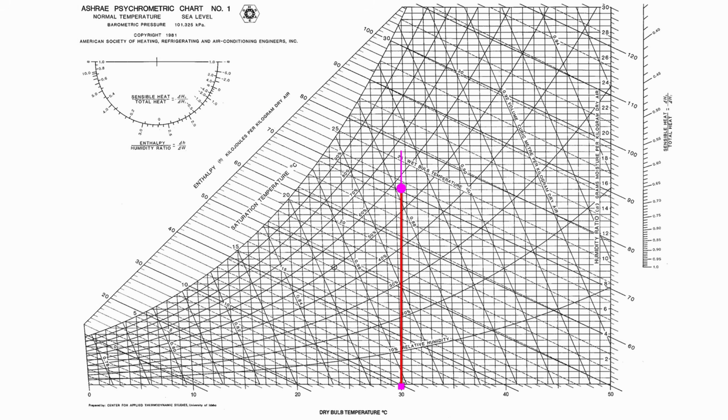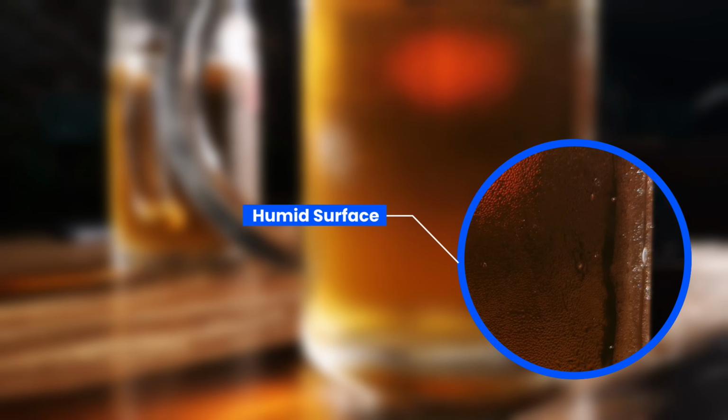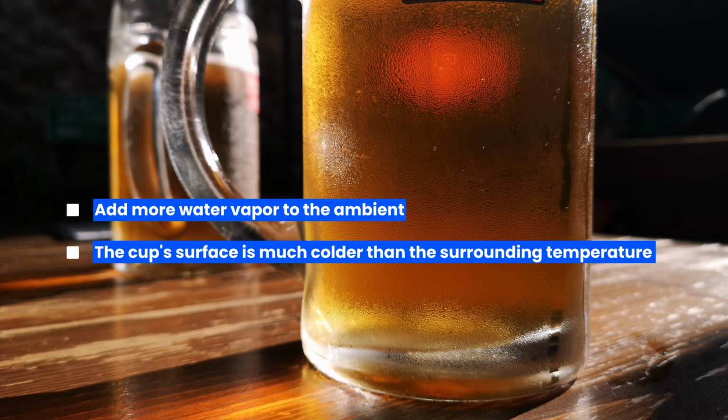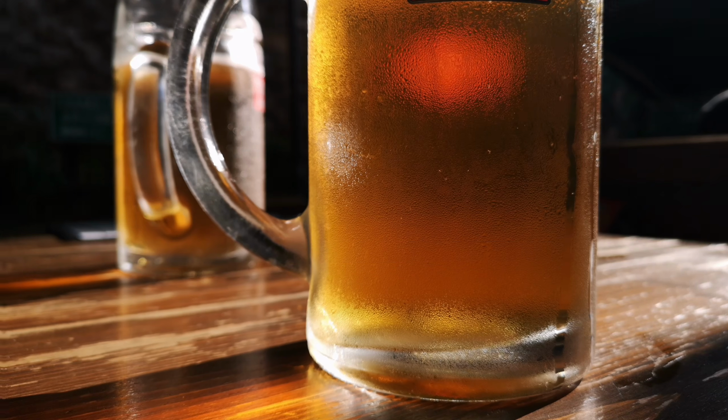Let's explore a scenario on the psychrometric chart where the water vapor partial pressure remains constant while the temperature decreases. At this point, we can trace the conditions to the saturation line, which marks the dew point. The dew point temperature is the point where the water vapor in the air becomes fully saturated. If you add more water vapor after this, or if the temperature drops below this level, condensation kicks in. In other words, the water vapor turns back into liquid form.